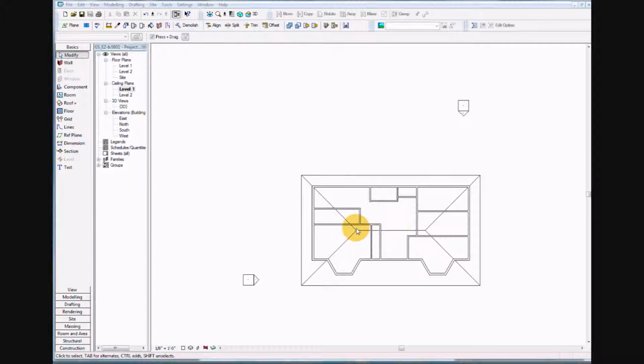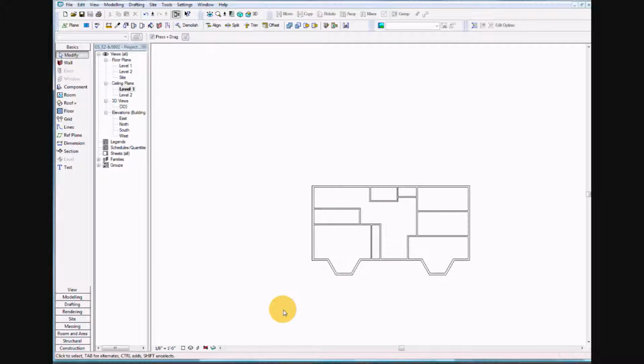So select the roof, hit the control on your keyboard, and then go ahead and it wants us to grab the elevation marker and then enter VH on our keyboard. Alright, and that just turned it off. And go ahead and undo it.